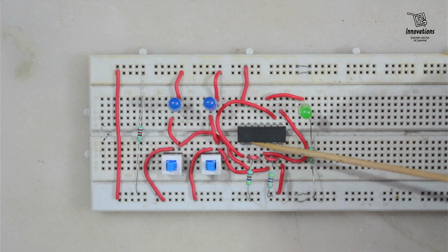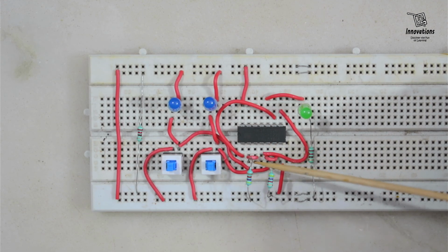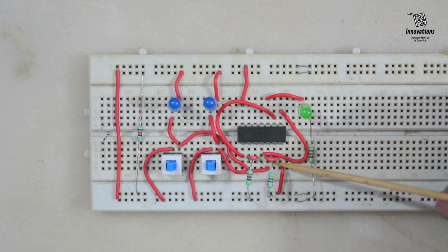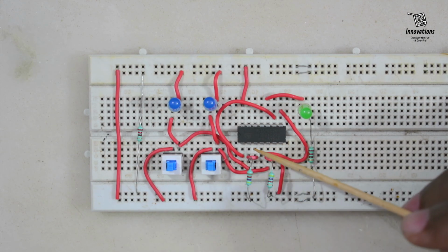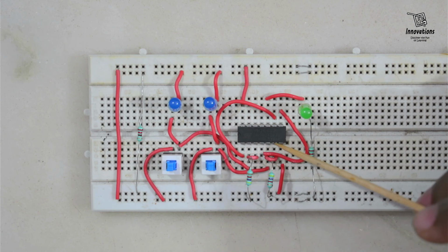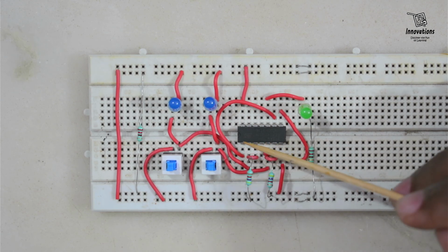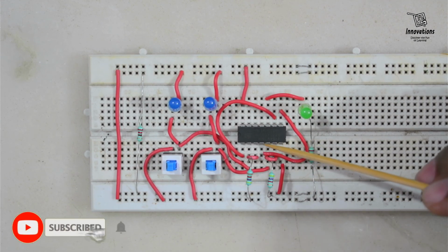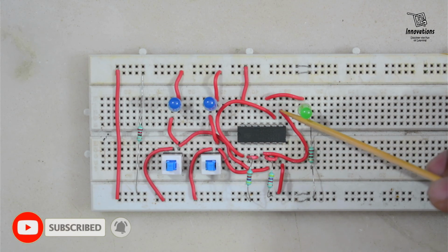We have interconnected the inputs of 2 segments. Segment 1, pin number 2, 3, we have joined using a jumper loop here. And pin number 5, 6, we have interconnected using a jumper loop here. We have given one input to pin number 2, 3 and another input to pin number 5, 6. And output of segment 1 from pin number 1 is connected to pin number 9, and output pin number 4 from segment 2 is connected to pin number 8.